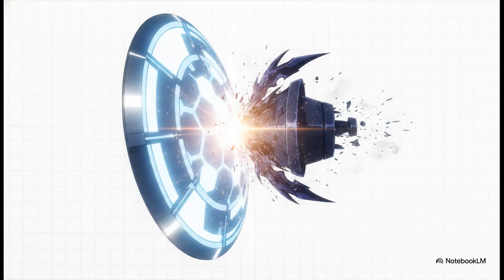Okay, this brings us to the golden rule of flexural design. The factored load the beam experiences must never, ever exceed its calculated ultimate capacity. MU is your ultimate design moment, which is mathematically defined as 1.5 times the sum of your dead load and live load moments. MR is your ultimate moment of resistance, basically the maximum muscular pushback your beam can offer. If MU surpasses MR, well, you have a failure. No two ways about it.